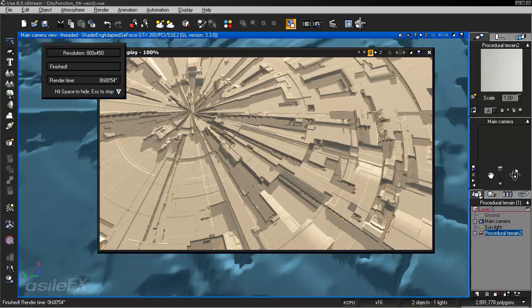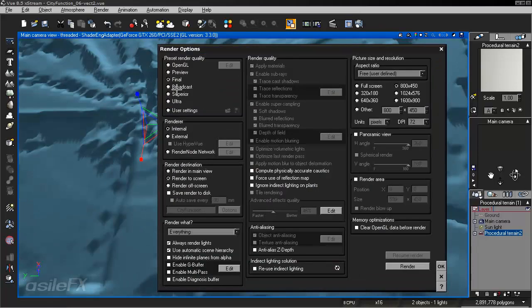So if rendering broadcast is taking too long to render, I would suggest rendering a final preset mode instead of switching over, because actually I think in this case, as of version 8, possibly even 7, the advanced effects quality in the preset was reduced to be equal between these two. It looks like it maybe just turns on basically an animation quality version of the final mode, having texture anti-aliasing and also the motion blur. So until you hit superior, you don't have an advanced effects quality that is different.